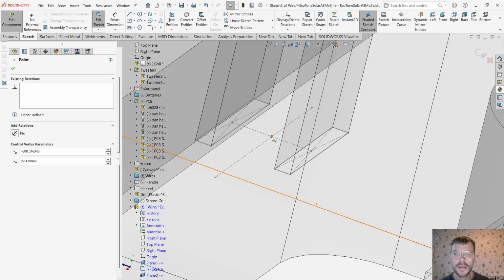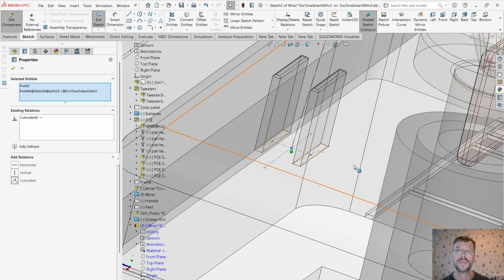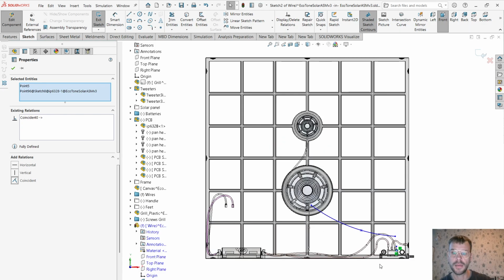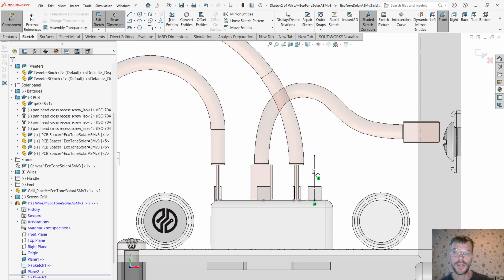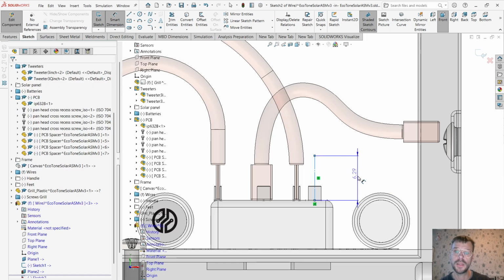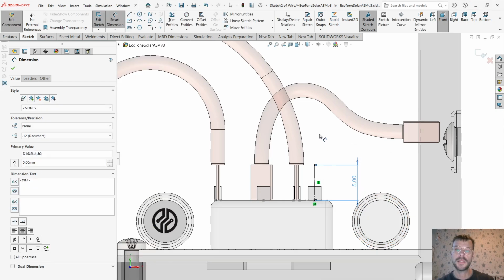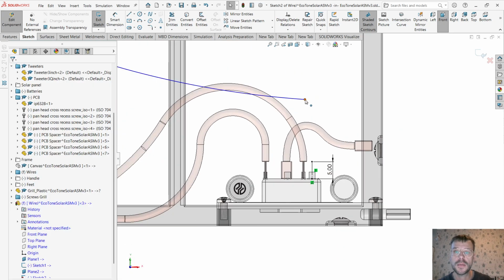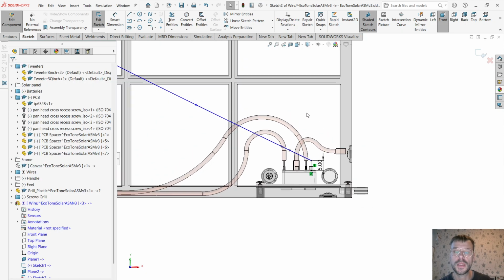And that point with Control held down, and coincident. Whoops, didn't like that view. This is okay. Letter D, the D key, gives me my dimensions tool, 5 millimeters. Select to exit.